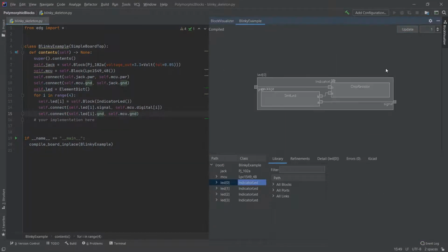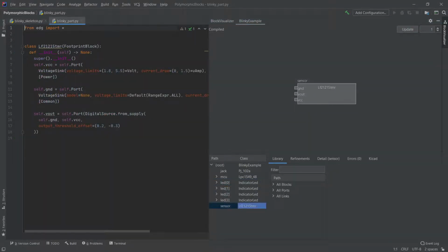If we were curious about the indicator LED circuit, we can click into one of them, which brings up a standard LED and resistor circuit. Mousing over the resistor brings up a summary tooltip, which shows the automatically derived constraint on resistance and the chosen part resistance. The IDE supports building subcircuits and components just like top-level designs, with ports added the same way as blocks.